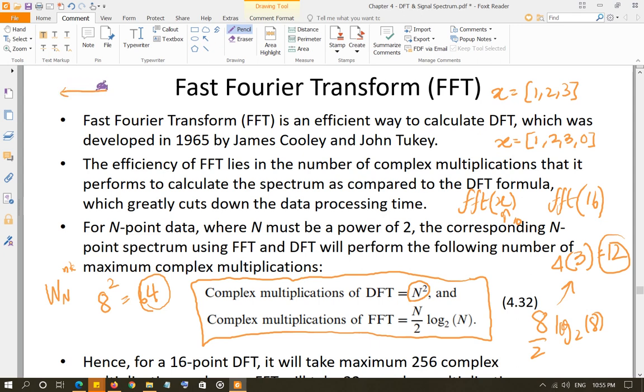Remember, you cut the signal to analyze for a specific time t0, and then you sample that signal, right? Now when you add zeros, you are extending that t0, because earlier your t0 had 3 points. You had 1, 2, 3, whatever. So now when you add a 0, 0, whatever, you are increasing the length of the input signal over which you are doing the FFT.